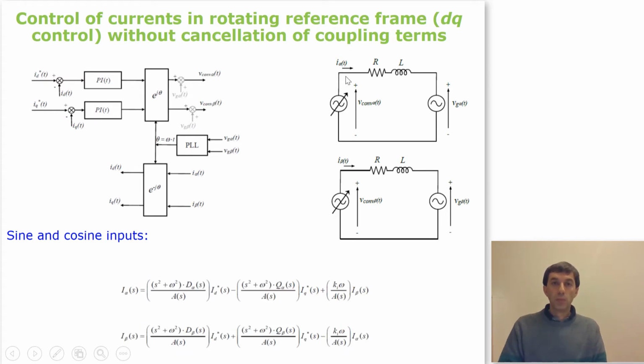We match both expressions of control and power circuit, but now without cancelling, without the feed-forward terms, we can obtain again transfer functions very similar to the previous ones, totally equivalent, but here these terms are equivalent to the previous ones obtained with the cancellations of the coupling terms, and the difference is in the coupling itself.